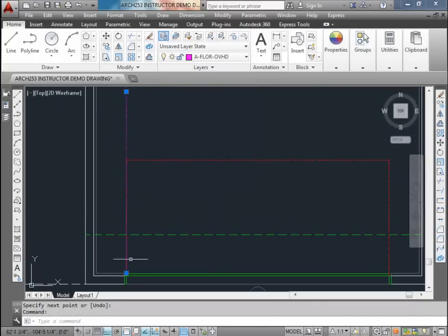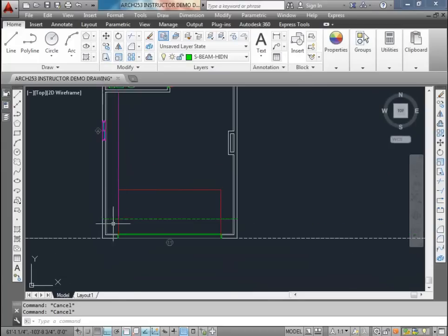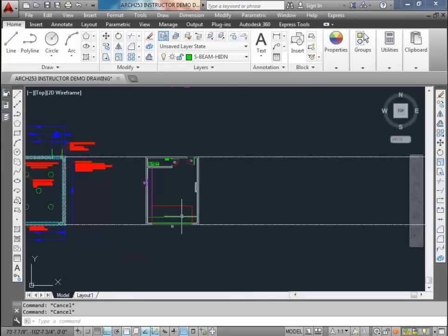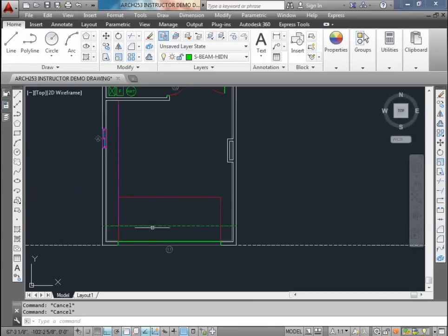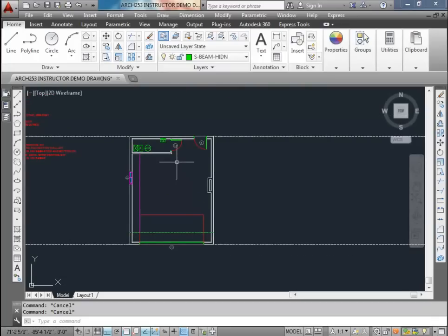And actually, this bulkhead should stop for sure at that beam location. It's not going to go any further than that because there's no wall further than that, right? There's nothing that it needs to service beyond this line here. This is the line of the main floor. So when we draw our main floor here, this is the front of that main floor. So your construction line, you can actually move it onto this line here because that's going to be where the main floor is.